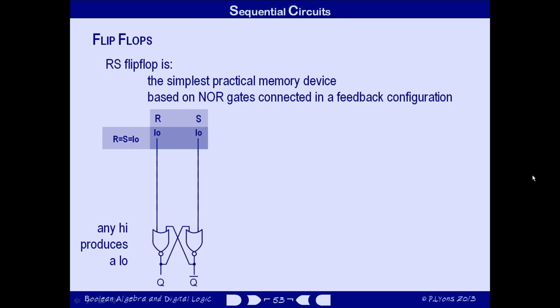Well, we simply consider two separate situations separately, first where it's a 0 and secondly where it's a 1. And because the circuit is symmetric, we only need to consider the output of one of the gates. Let's make it the left gate, the one that's outputting the signal we call Q. We'll start with a 0 output from Q and show this value also in the table where there's an entry for Q. I've connected this into the table with a dashed line to indicate that the table is not actually setting this value. And in fact, since the value on this output is controlled by the circuit, it could change. So the value we assume to start with may become invalid during the operation of the circuit.